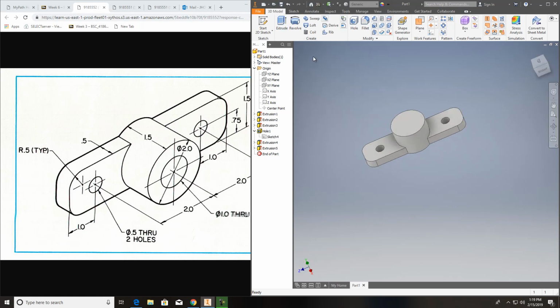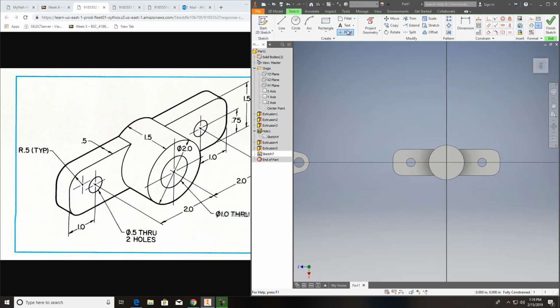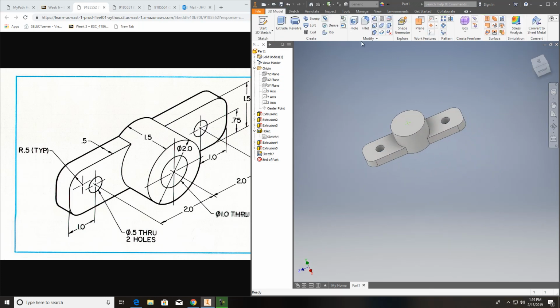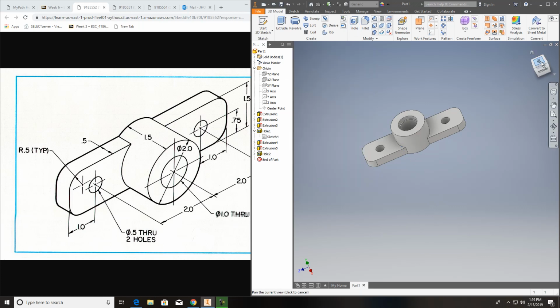And then I'm just going to new sketch it again, right on the face of it. Put us a point on there. Boom. Finish sketch. Go to our hole command and modify. And it's a 1 inch through hole. It's just a through hole, simple hole, and it's 1 inch, 1 inch all the way through. And something messed up.